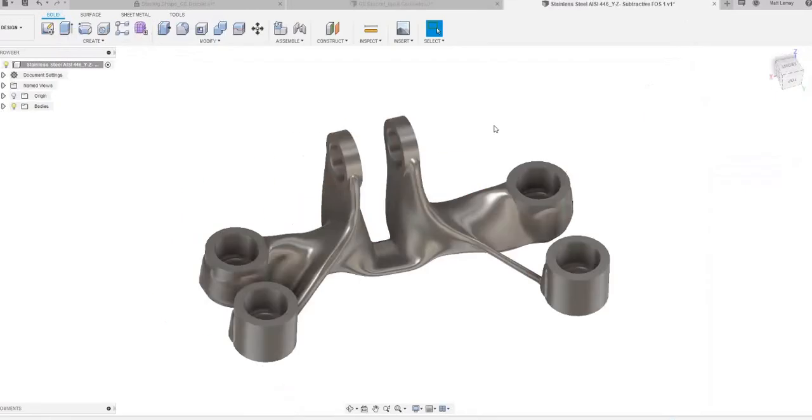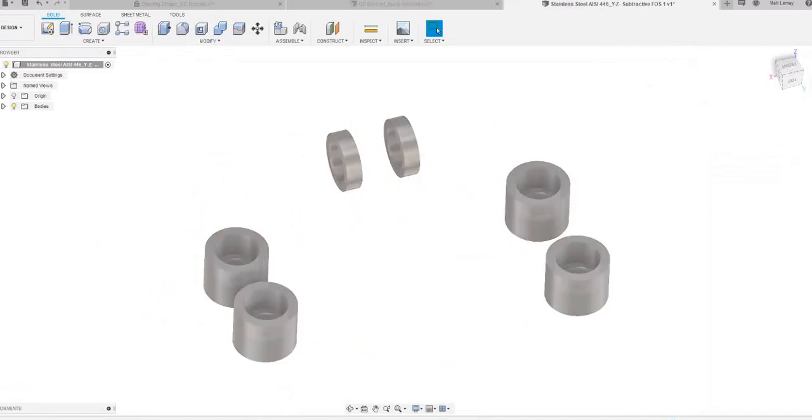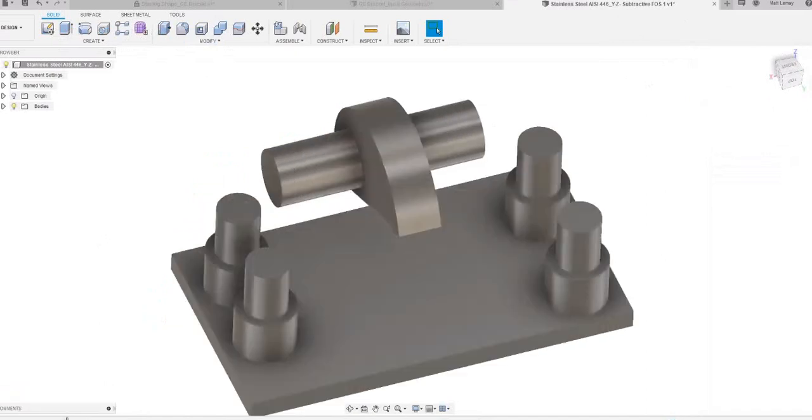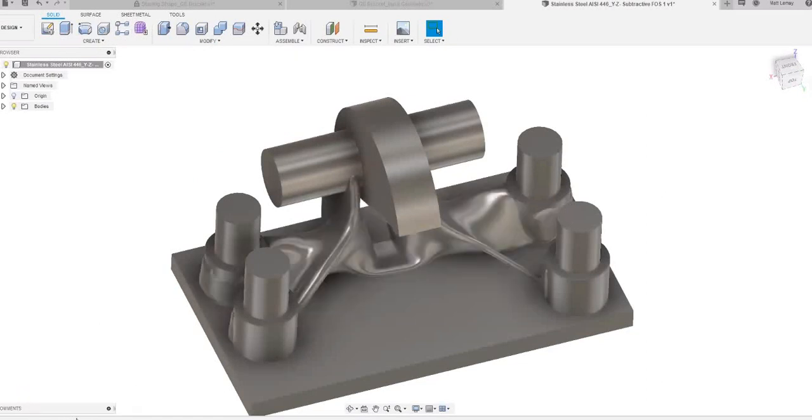When you do that, what you get back is what you're seeing on the screen, right? So you get one solid part for that. And then at the bottom, you'll see a timeline. The first thing it does is bring in our preserved geometries. It then brings in our obstacle geometries. It takes all this generated organic geometry and creates what's called a T-splines model from that.